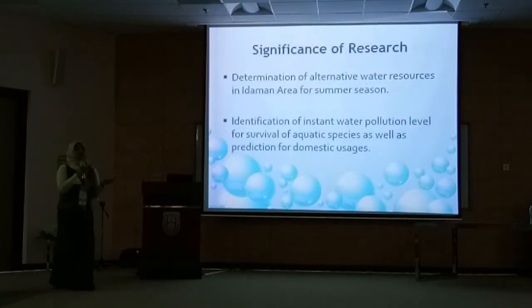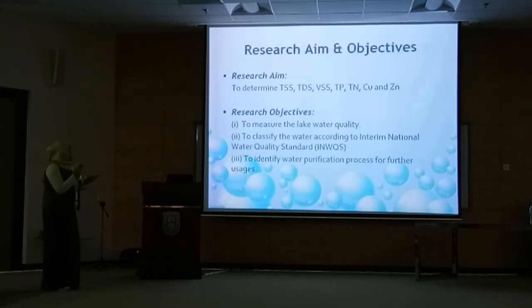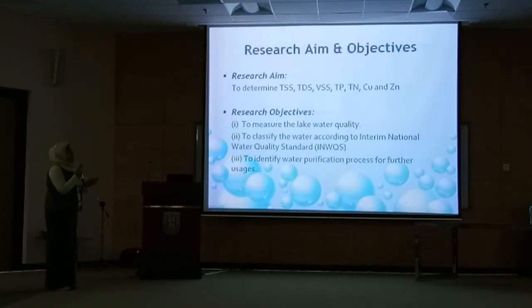The research was significant as the Malaysian water sector is looking for alternative water resources, especially for the summer season. Many experiments are going on in Malaysia on lake water. Our research aim was to determine TSS, TDS, VSS, TP, TN, copper and zinc. The objectives were to measure the lake water quality, classify the water according to the Interim National Water Quality Standards for Malaysia, and identify some purification processes for further usage.